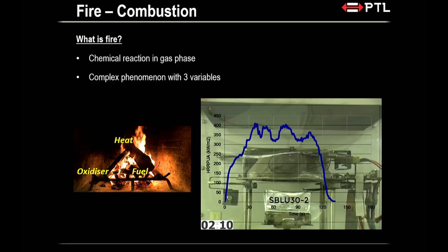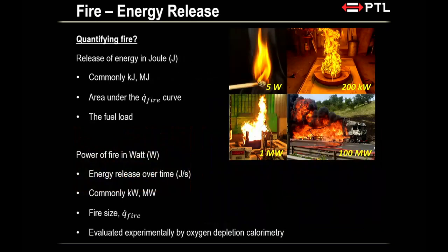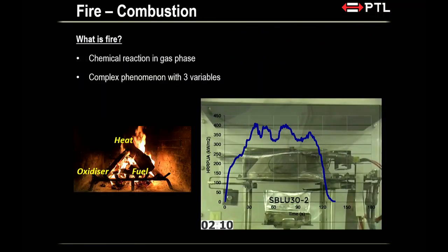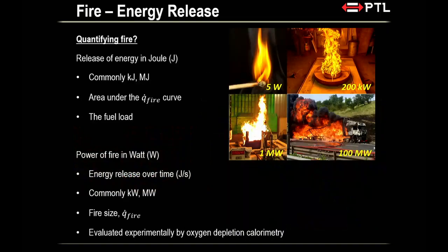So every fire goes through this phase, whether it's out in the open or if you stick it inside a compartment, it will go through these phases. Why does it go up and down on the top? It is a bit of a plateau, so if you look at the value, it actually doesn't change much. It sort of hovers about 350. My apology, the wording is a bit small, but it is really a plateau. So if you increase the heat source, you might get a taller peak. So it changes slightly.